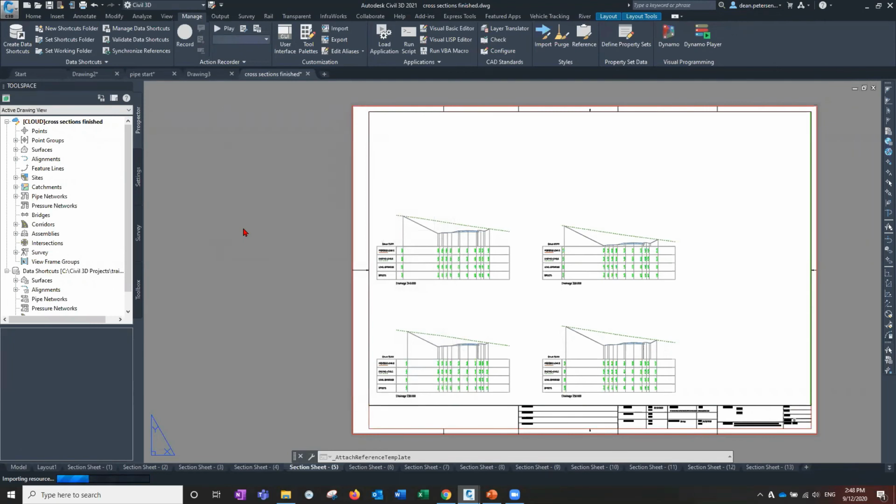And this apparently did not work before 2021.1 using BIM 360. Now it does. We'll just prove that it does in a moment. Getting close to time, but there's only one more thing to look at after this. Okay, you can see it's actually changed my standard corridor style there to have the purple dots on it, which I don't particularly like, but that was obviously part of that template, the Vic Roads one.